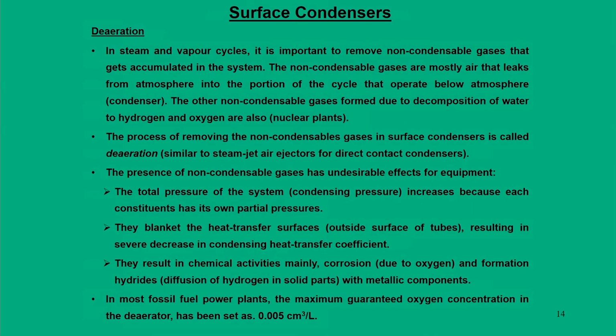Another important aspect of the surface condenser we are now going to see is deaeration, the deaerator. In steam and vapor power cycles, it is important to remove non-condensable gases that get accumulated in the system.